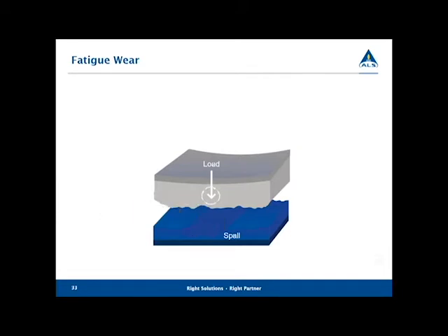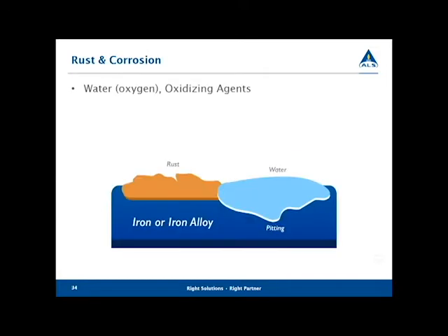And the interesting thing about wear failure is that when we do ferrography, which is an analytical examination, obviously, of wear debris, we never see just one type of wear debris. We see adhesive wear, we see abrasive wear, we see fatigue wear, many different things. Usually a preponderance of maybe one, but there's several different mechanisms at play, because fatigue wear can lead on to abrasive wear. And we'll explore erosive wear in a minute.